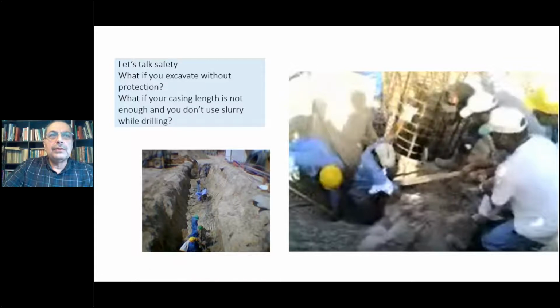You need to check trench stability even when you are drilling, for example, diaphragm walls. You have huge machines on the sides working, excavating for the diaphragm wall, and you did not check how much guide wall depth you need to be sure that there will be no collapse of the soil that the machine is working on and its platform into the trench itself.